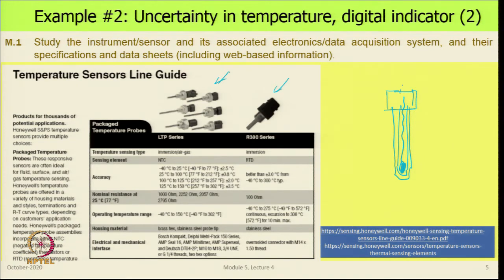Finally, there will be wires which can be connected, and this side you have arrangements to fix it to something else. So, this is the fixing arrangement here, and from this your wires can be taken out. There will be a connector inside which has screws on which you can connect it, and the sensor is sitting inside this stainless steel tube.